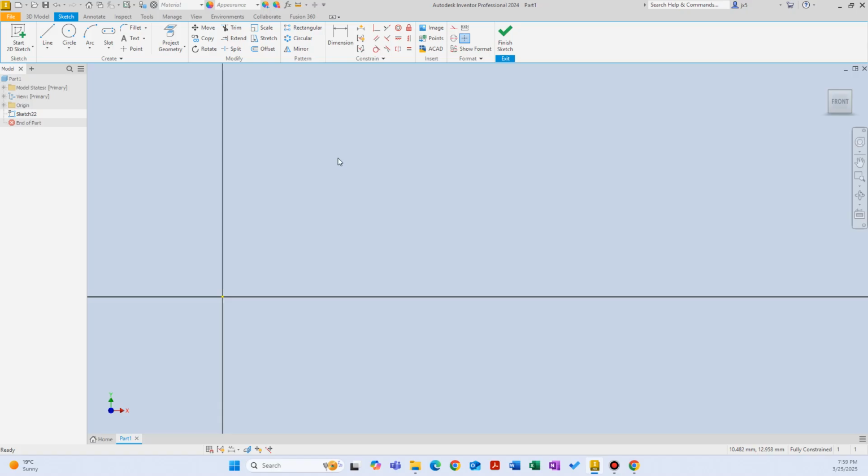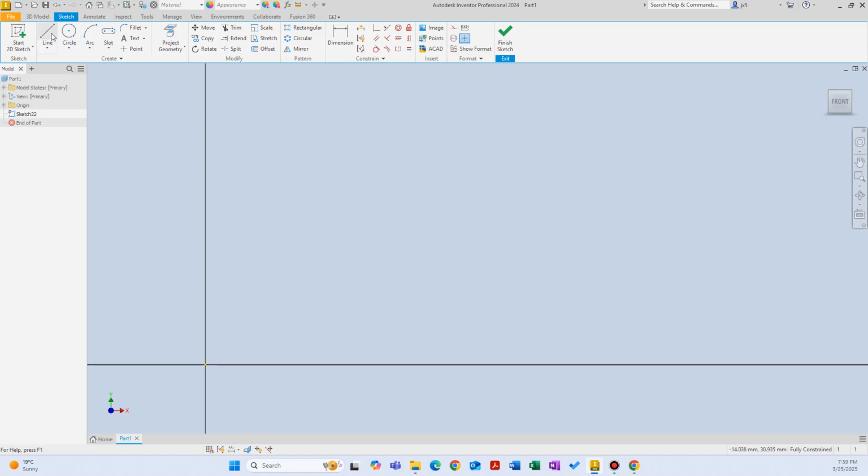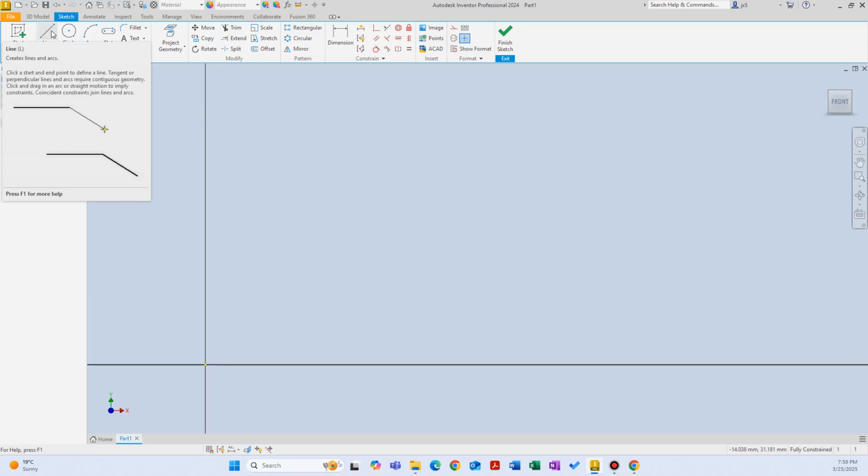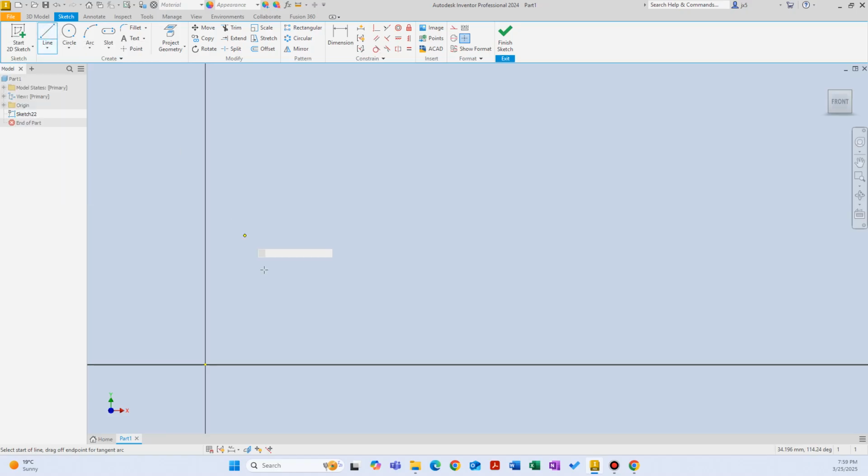Another thing that I wanted to mention before we end this video is creating arcs while drawing lines. We did not talk about that as we covered drawing lines. So if I draw a line here, and let's say I draw my second line here, my third line, again, is a straight line. But I don't want this to be a straight line. I want this to be an arc. What I can do is come to this endpoint and hold the left mouse button, and that's going to start creating an arc.